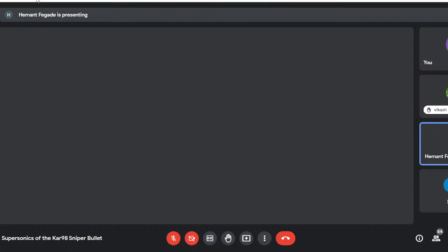So this is a pressure graph, or this is how pressure behaves. The yellow part or the red part that you are seeing are the color codings. Basically, your pressure is highest over here, and red means highest, blue means the lowest. This color coding might be different from the video, but that's how the general color coding is in Ansys or in any of the CFD software. When you are moving in this region, this is how your pressure is going to generate or move.